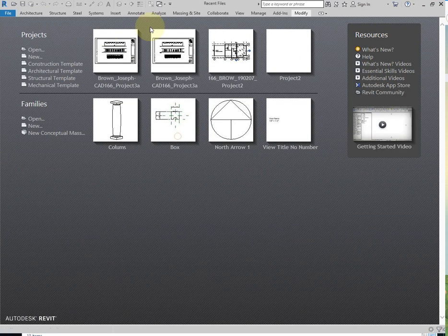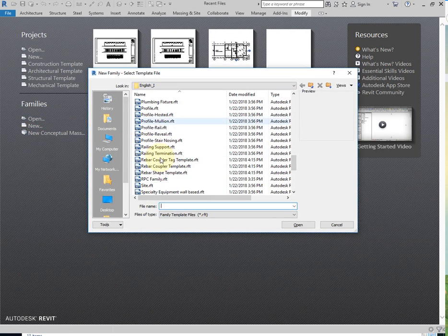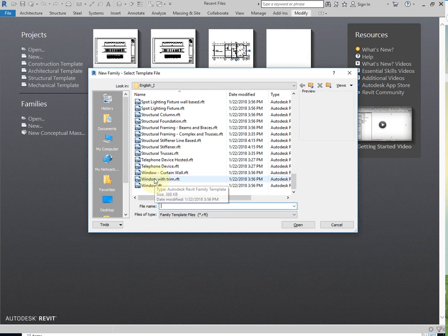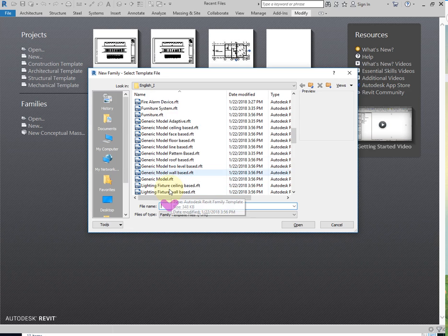So this next one, we're going to talk about the visibility parameter and materials. I'm going to make a quick little tile rack for a wall, and then we'll apply materials to the components of it. I'm going to start a new family again, and I'm going to make this a wall-based generic family.